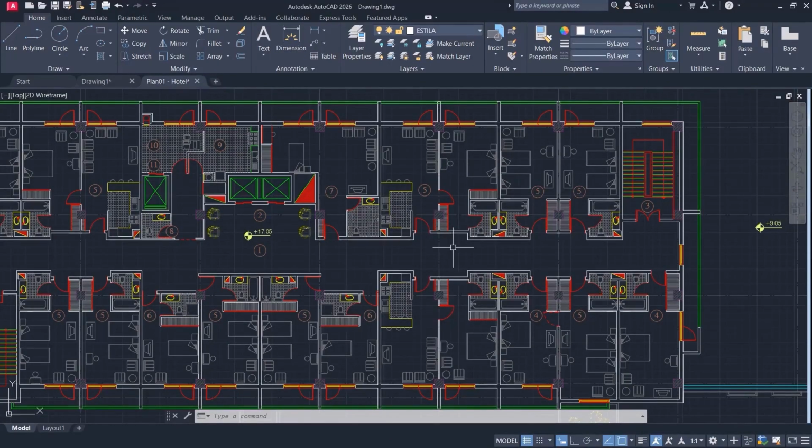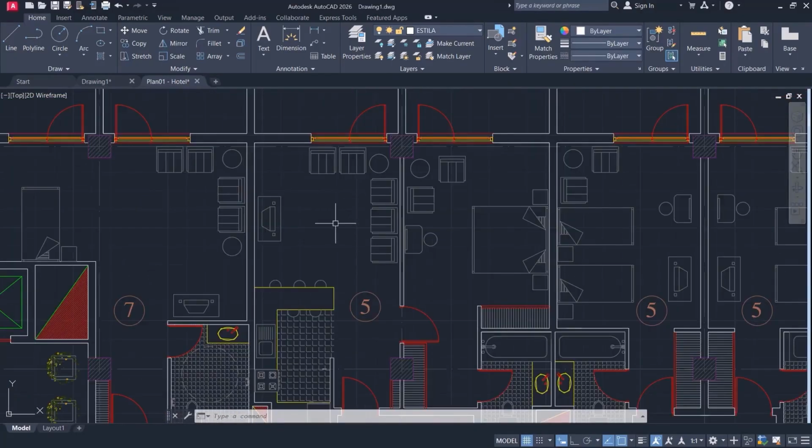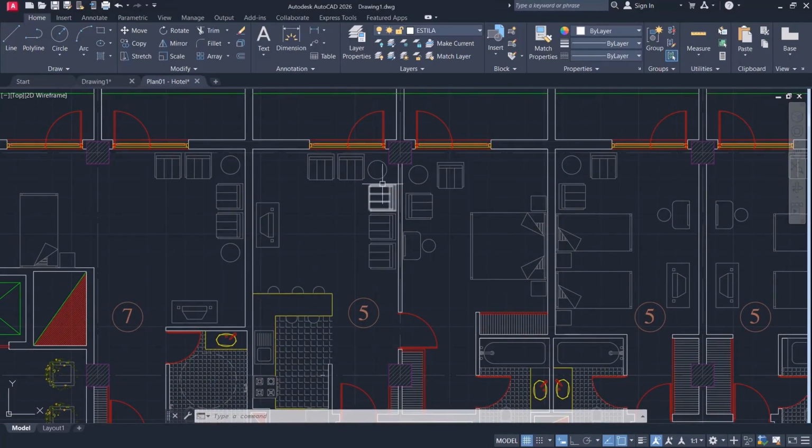The group command is used to categorize different objects, and by placing our various objects and drawings into a group, we can perform certain similar actions on the entire group instead of having to do them on each individual member. For example, what kind of things? Look, if we enter this room, in its living area we can see that the furniture objects are all separate from each other.